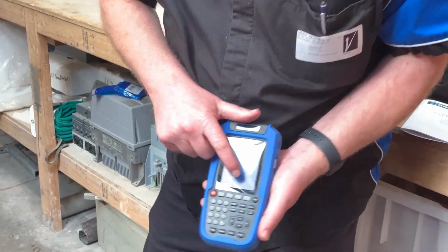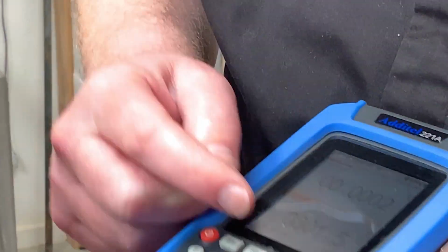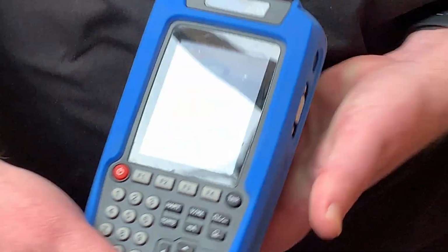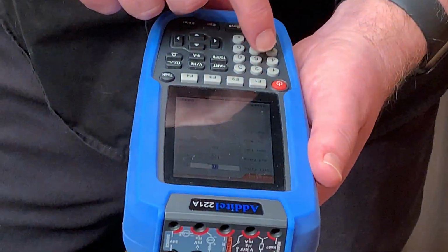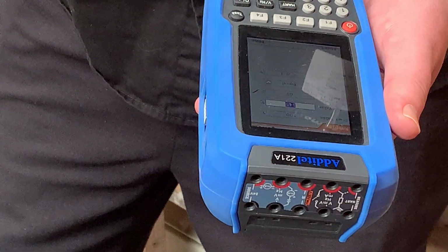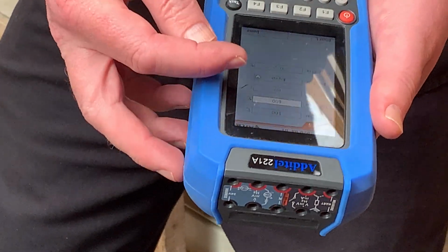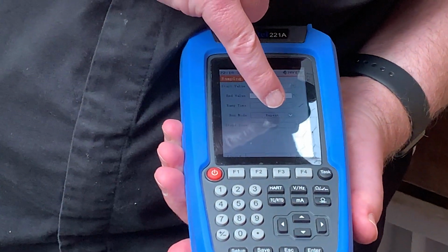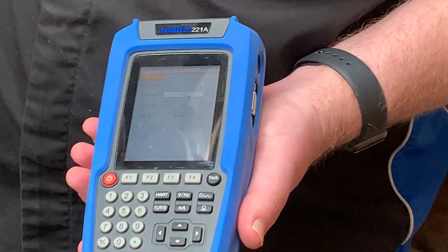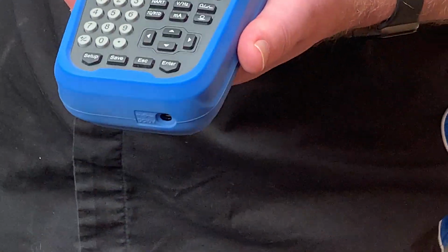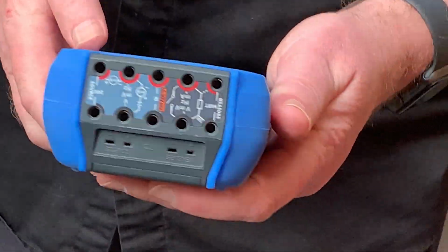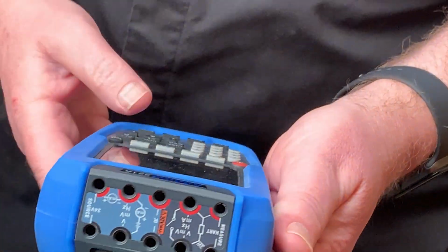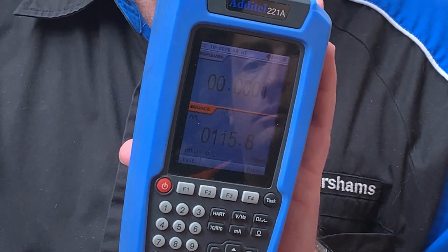Yeah. So you see here at the bottom of the screen, there's a LCD ramp. So F3 button. These are soft buttons. So if we hit F3 for ramp, we might say we want to ramp between 100 and 400 degrees C over 60 seconds, for example, and I want to do it in 0.2 degree steps, and I want it to repeat up and down, up and down, up and down. Connect it up as per this, and we go. Start, you can see the temperature climbing in 0.2 degree steps.